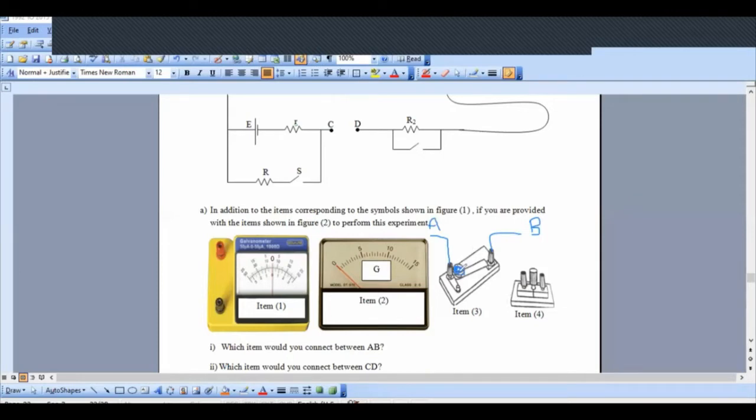Can you see? Once this knob is pressed downward by using your finger, this metal piece will contact this metal piece. Then only the switch is completed. But if you slightly remove the finger, what will happen? The circuit will be open. So it means you have to always press this knob downward to operate the circuit.